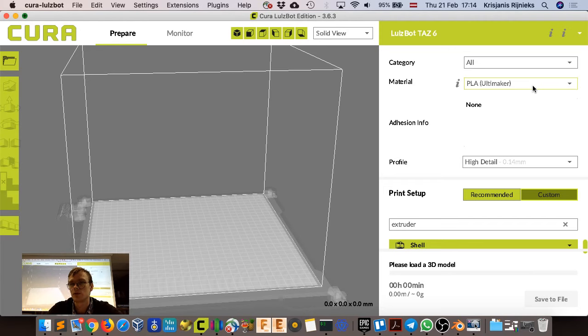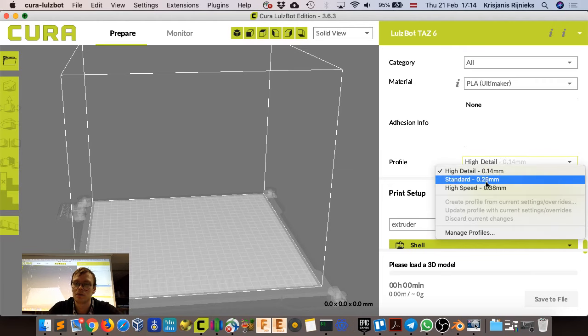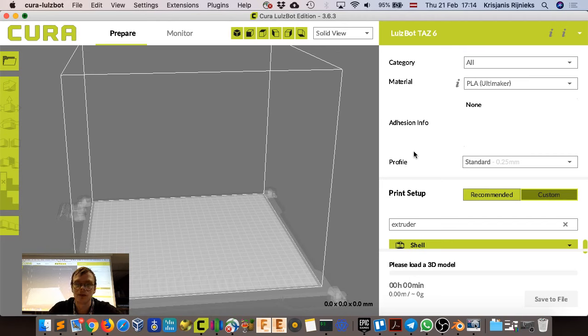But most of the PLA plastics have similar properties, so they melt. The melting point is between 210 and 220 degrees. This is what I'm going to assume. So yeah, and then you can choose the detail level of your print and some other settings, but these become important after you import the actual model that you want to print.